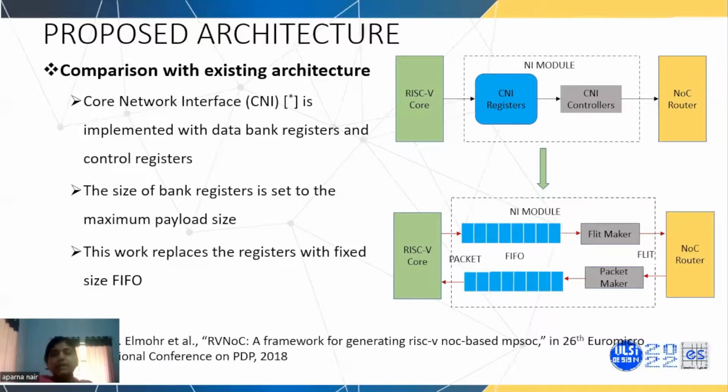We could observe that there is certainly an improvement in the performance of our NI module when we replace these registers with a fixed size FIFO. In the literature work, the size of these registers depends on the size of the payload data, but here we have used a fixed size FIFO.